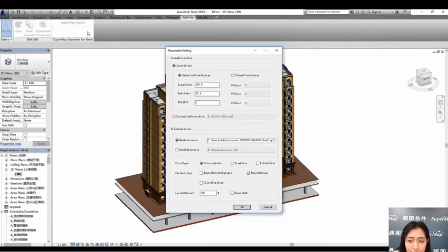The insertion point is the coordinates of the control point, and where the model is placed in the three-dimensional space when the model is exported, according to the difference of the projection. It is divided into a spherical insertion point and a plane insertion point. When we export this model, the insertion point and the project base point are points with the same name, and the vertices of the model are exported relative to this position.